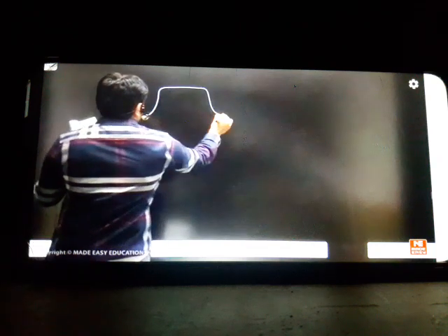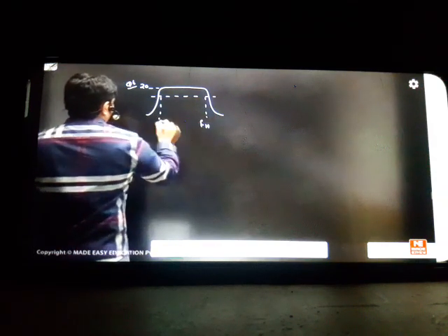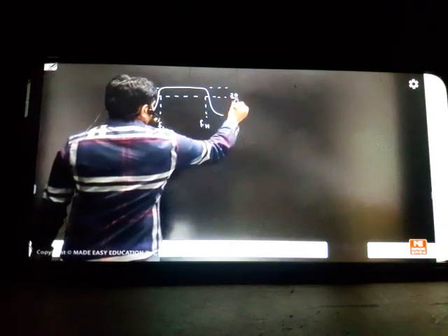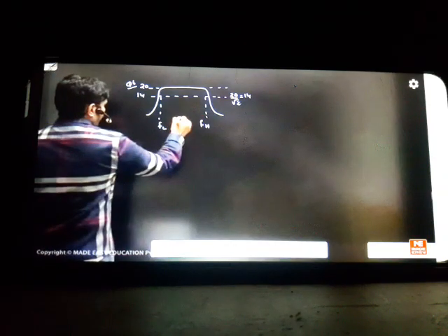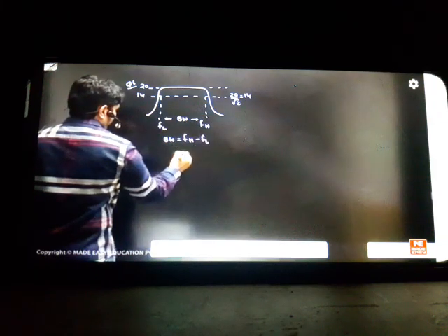Next, going to question number 6 in the class. An RC coupled amplifier has a mid band gain of 20. Measured at particular frequencies, one is FL and one is FH, the gain is 14. What is this 14? It is 20 by root 2, which is about 14. At this 14 we get the lower cutoff frequency and higher cutoff frequency. He is asking what will be the likely phase shift at this frequency. Generally the bandwidth is considered as FH minus FL, but here we are considering only FH.